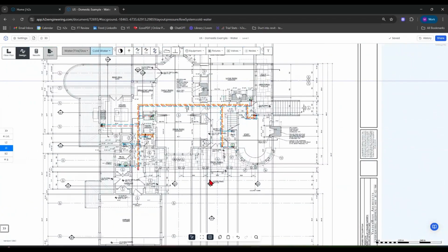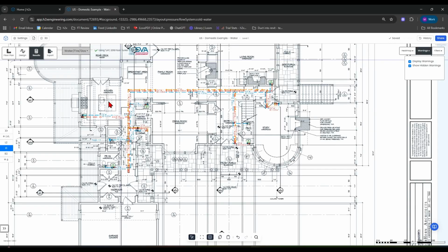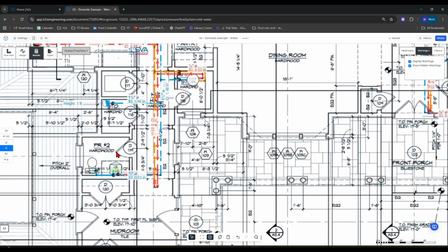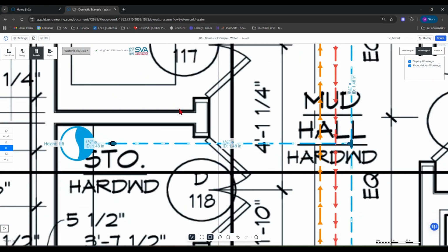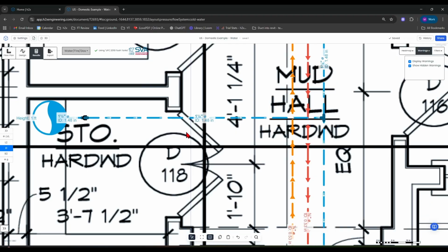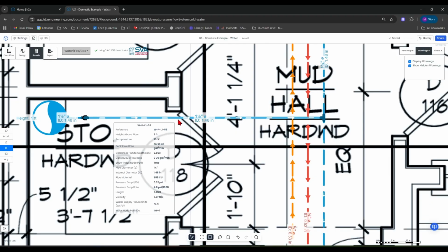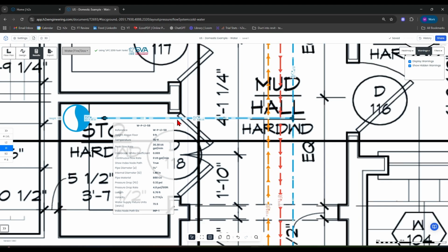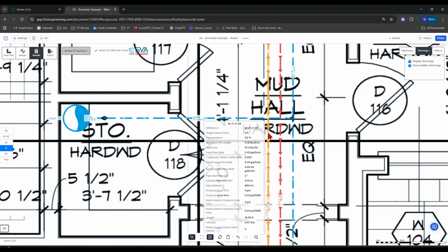Now that the design is at this stage, you can hit results, and h2x is going to give you the pipe size and requirements of that system. So you can see on our main incoming water, we have a 1.5 inch pipe that has 36.38 gallons per minute associated to it, again based on that Hunter's curve diversification. h2x will also calculate the pressure loss through each pipe, like so. See there, we work in PSI per 100 foot.